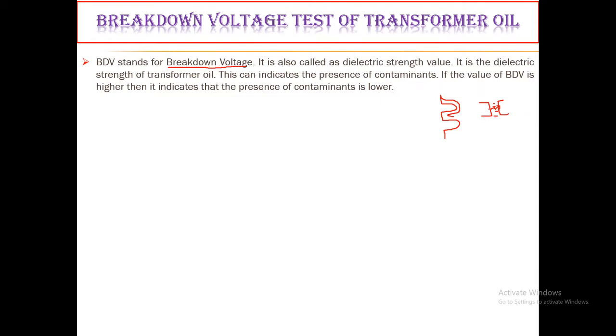So why are we using this? In case of liquid or gaseous dielectrics, you can use the word flashover, but in case of a solid, flashover is applicable only to a spark observed over the surface into the air. Ultimately, the process that we are observing is the breakdown of the gap between the two electrodes, and that is known as a breakdown of an insulation.